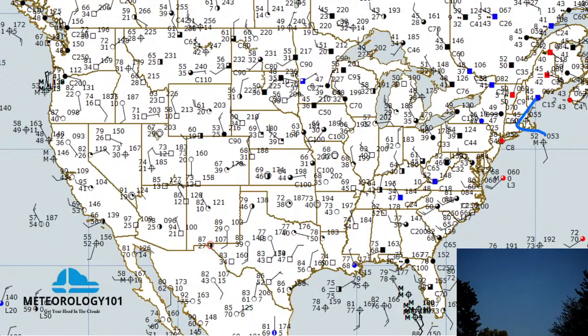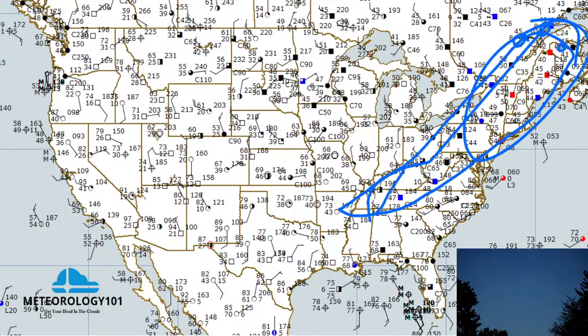But anyway, low pressure. We got IFR conditions, which is basically the ceiling is less than 1,000 feet or less than 1 mile visibility. So we got mist with the two little lines there for weather indication, and then this looks like rain and/or maybe drizzle, and then there's some light rain, light rain, light rain. Overcast skies, cloudy all through here. So if we looked at satellite, we'd have pretty much clouds all through this area.